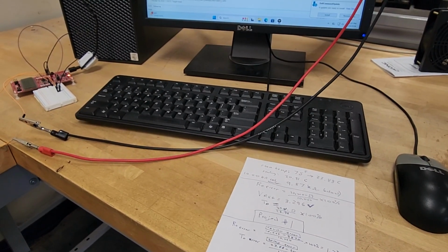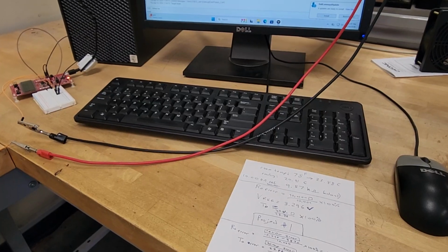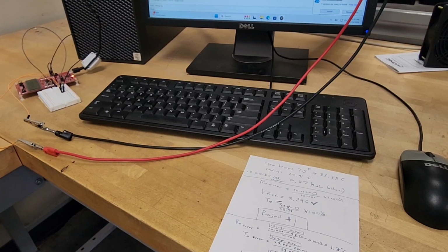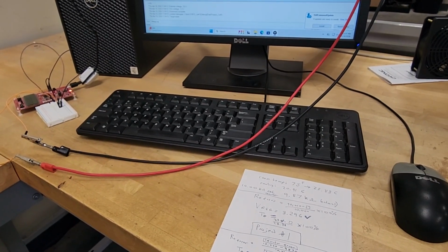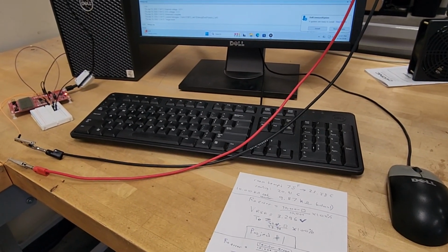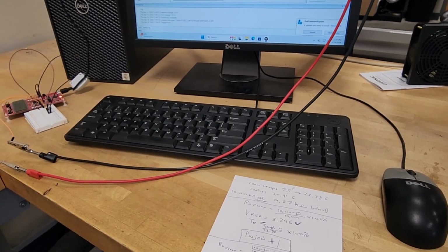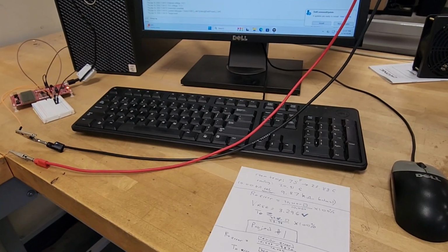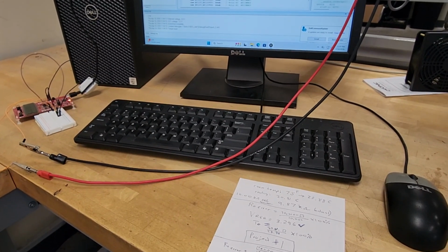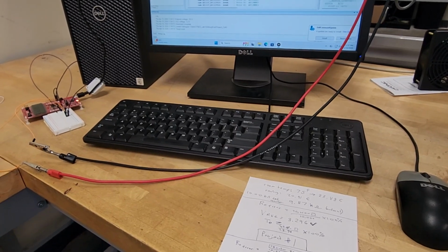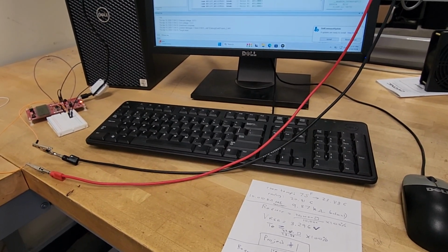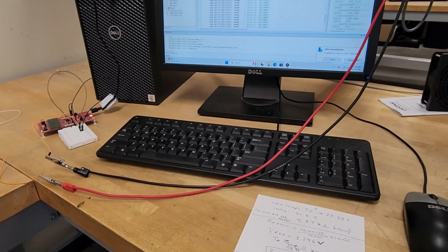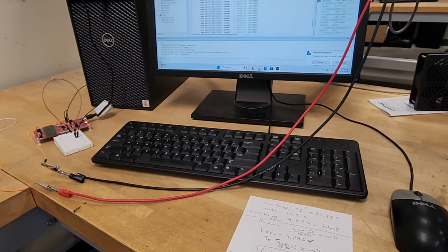A thermistor with a 1% or 5% tolerance will introduce a corresponding temperature offset. T naught error comes from the uncertainty in the reference temperature used in the equation. The beta formula assumes that R naught is measured exactly at 25 degrees Celsius or 298.15 Kelvin. If the real calibration temperature differs from this assumed T naught, the computed temperature will be slightly off. So even a small error in T naught propagates through the logarithmic term and causes a temperature shift across the entire measurement range.